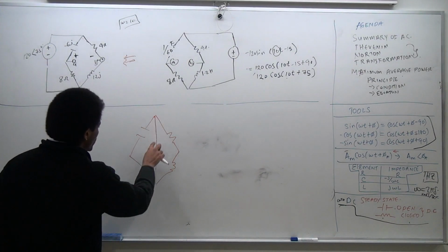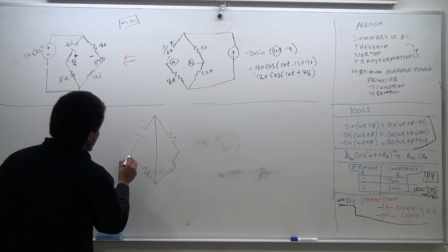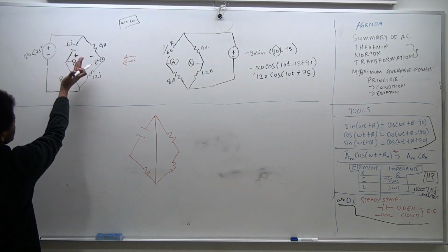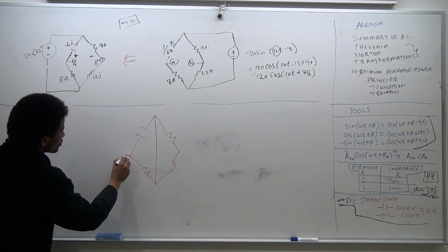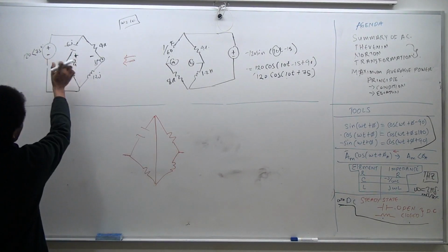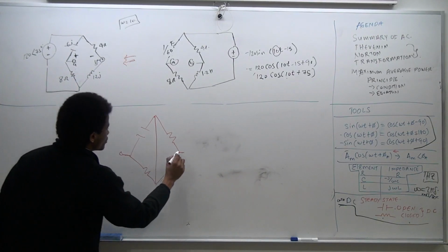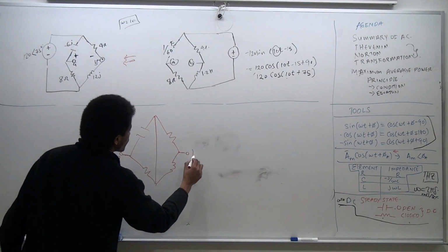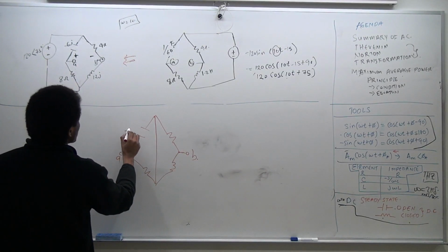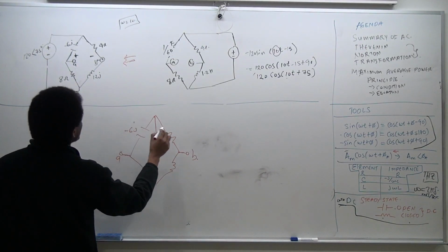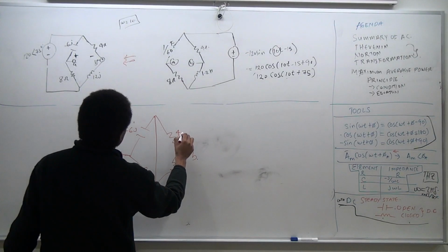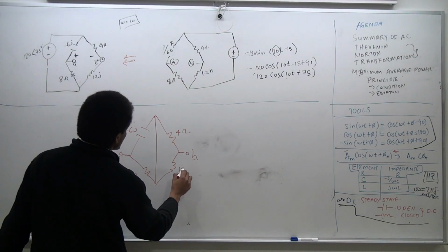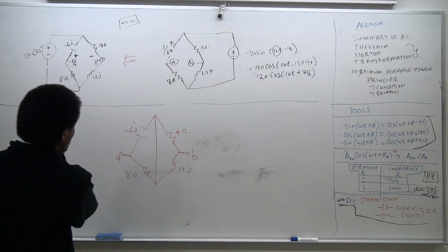This is why this wire comes into the picture. Then I'm just going to take the A reference and flip it to the left so you can see what's going on. I've not changed the problem, I've just turned the wire over. So you've got A, you've got B, and nothing has changed: 6j, 4 ohm, 8 ohm, and 12j, the impedance of the inductor.